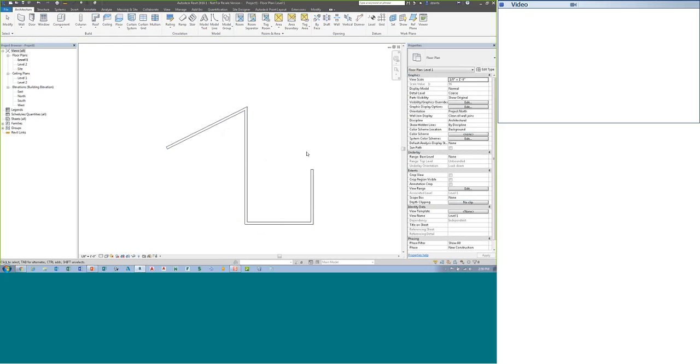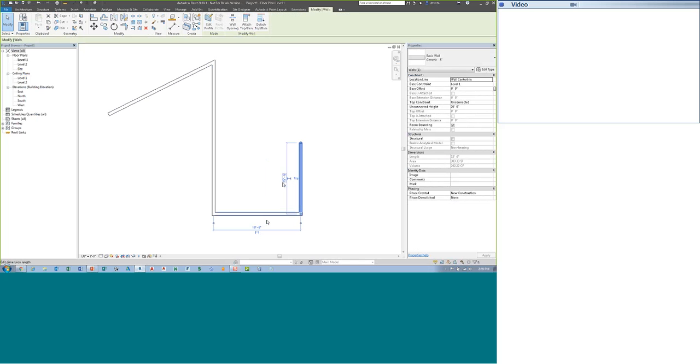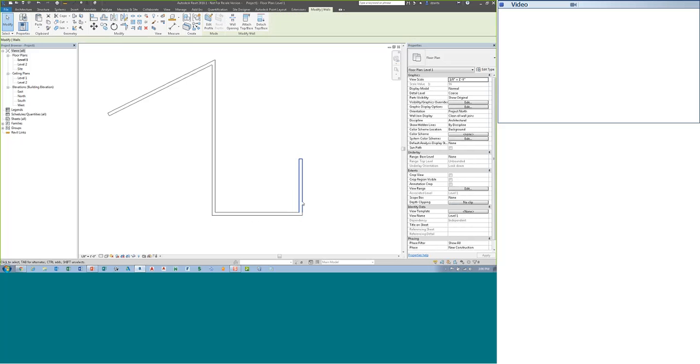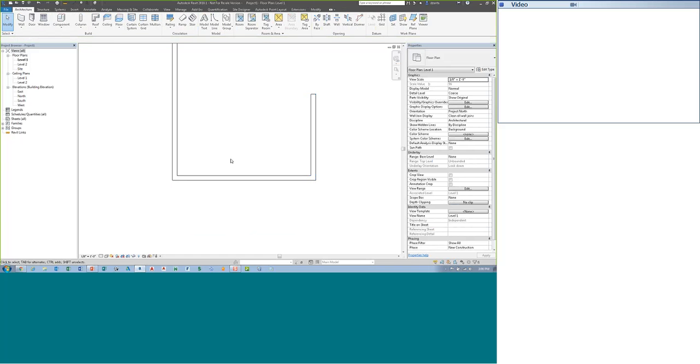Okay? If you select an entity, the temporary dimensions that pop up give you a lot of control, and you can go ahead and click any blue text of the temporary dimension, make a change, and the object will adjust. If you select an entity, you can left-click these move witness line dots, and it will adjust what it's actually dimensioning, face-to-face, center, or other side of face. And again, you can change the dimension and adjust.